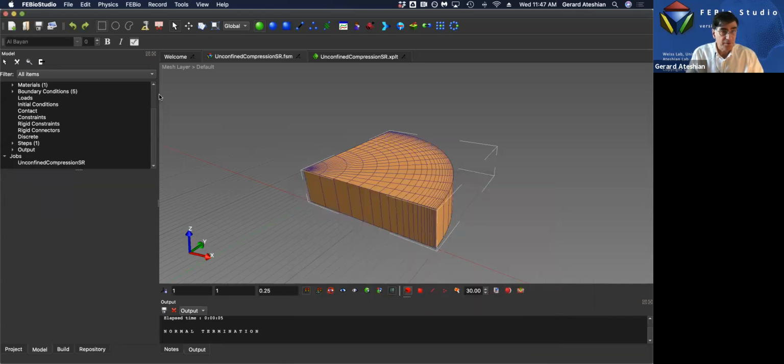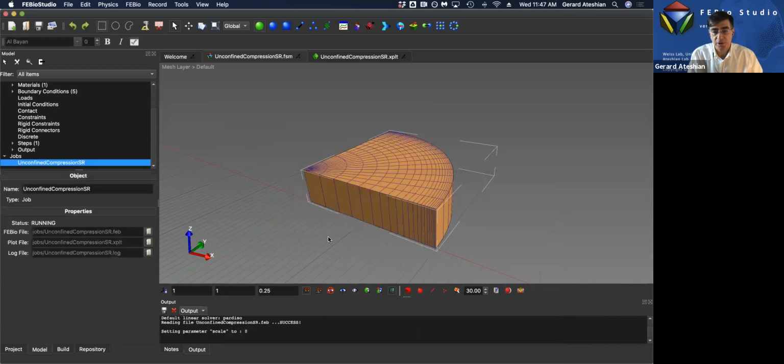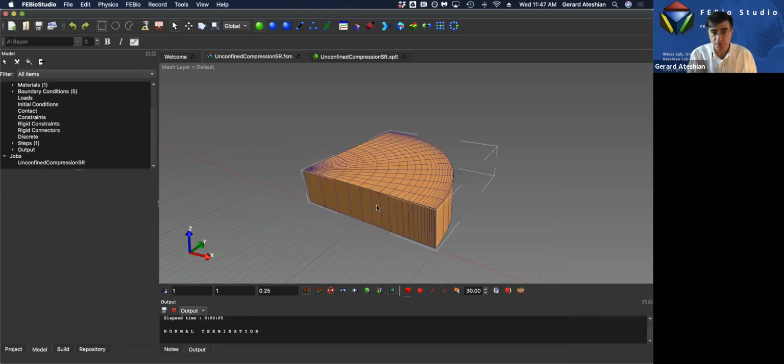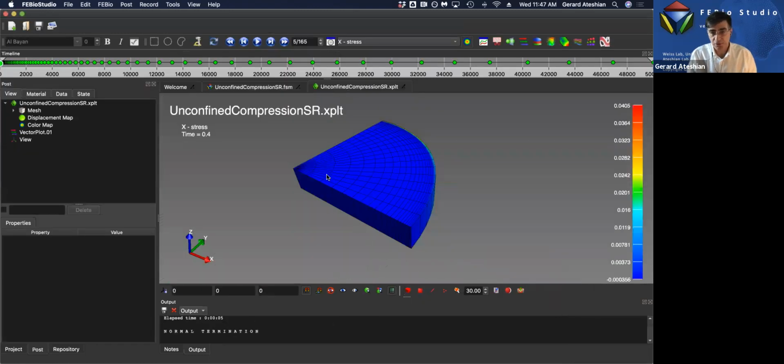Okay. So I've added these, and I'm going to rerun the analysis. That's the problem. If you forgot to add a plot variable, you actually have to rerun the analysis. We're very lucky here that the analysis runs very quickly, but if you were unlucky, it took 3 days to run the analysis and you realize you forgot to output something, remember that beforehand.